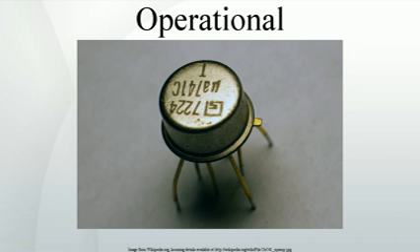Classification by internal compensation. Op-amps may suffer from high-frequency instability in some negative feedback circuits unless a small compensation capacitor modifies the phase and frequency responses. Op-amps with a built-in capacitor are termed compensated, or perhaps compensated for closed-loop gains down to, say, 5. All others are considered uncompensated.